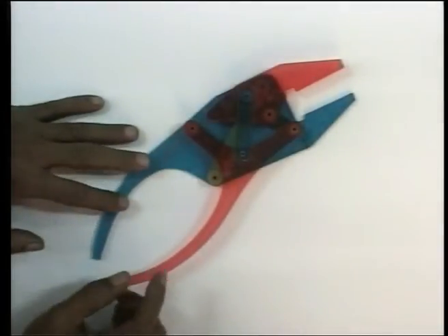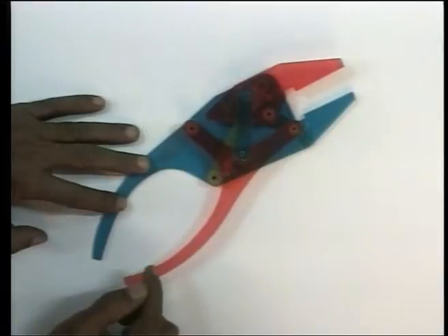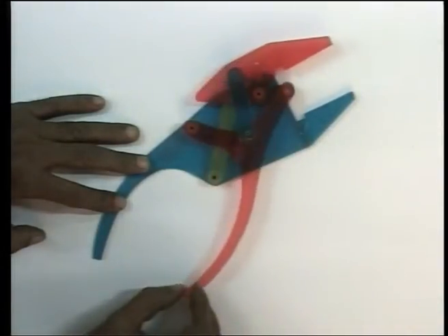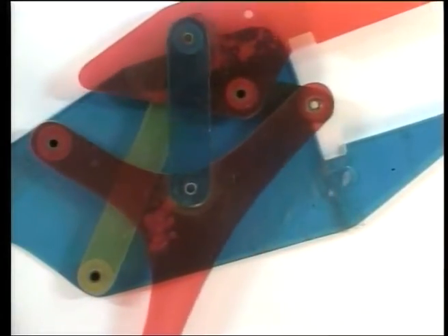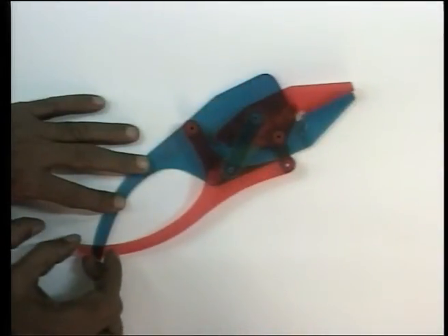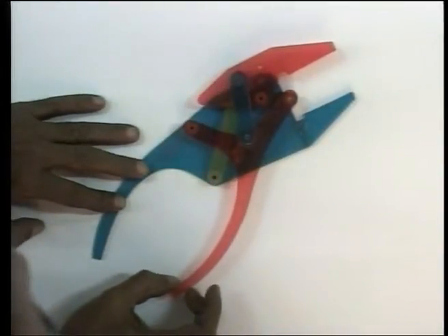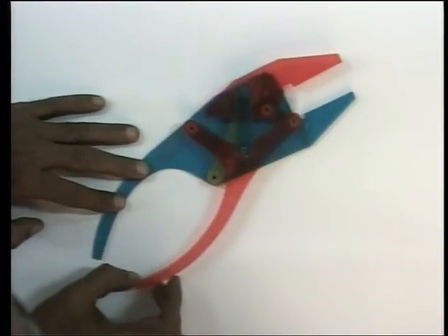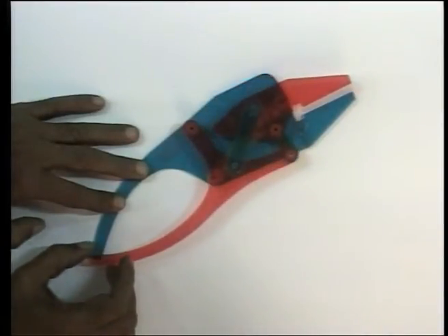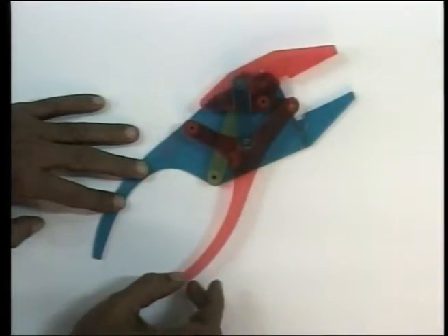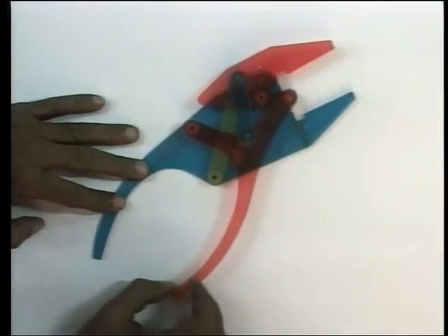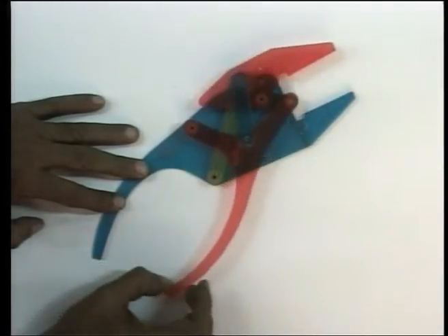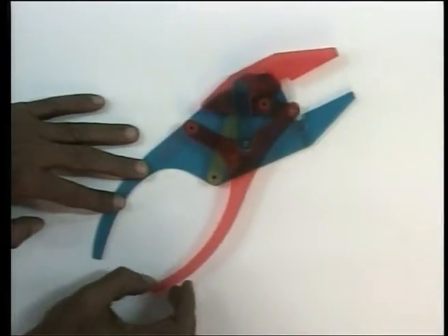However, we can design a parallel jaw pliers by using a suitable mechanism. Using this mechanism, as we see, the upper jaw is moving parallel to the lower jaw, and consequently it will provide a very good grip on a flat object. So, in such mechanisms, the generation of the specific motion characteristics is of primary interest rather than the forces or torque involved.